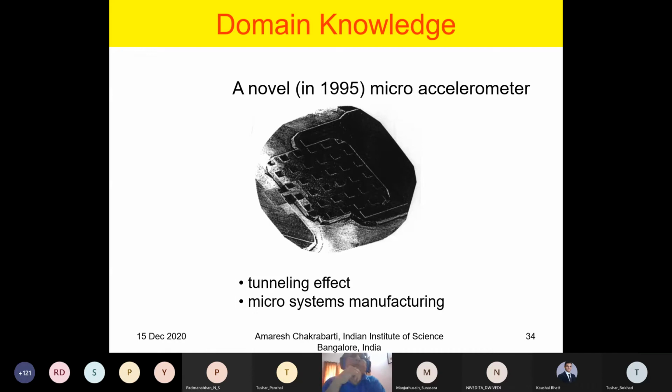And what you see, for those who have a technical background will probably understand, the middle bit is a small mass, okay, and the side two lips that you see here and here, these are like an overhang cantilever, like a beam, and so when acceleration happens, this thing goes up and down because of the stiffness of these two beams here, and there is a small protrusion here at the front.